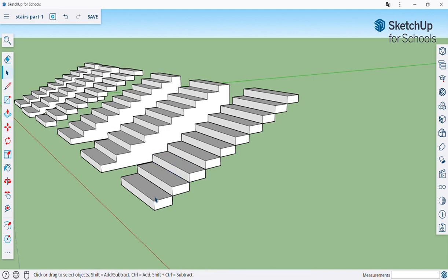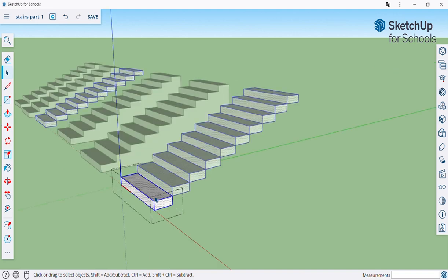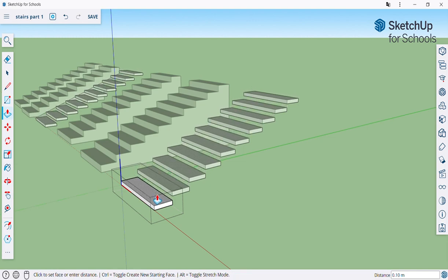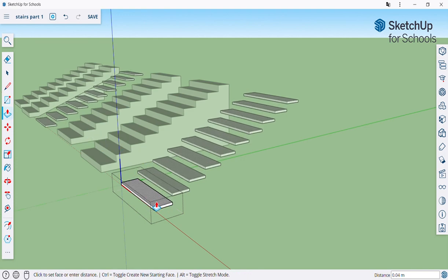If you use the select tool and double click inside of a component, and let's say use the push tool, whatever you do on this step will affect the rest. In this case it also affects these ones because I used the same name for the component, so no stress about it. Okay, so suddenly we get floating stairs and it looks awesome.